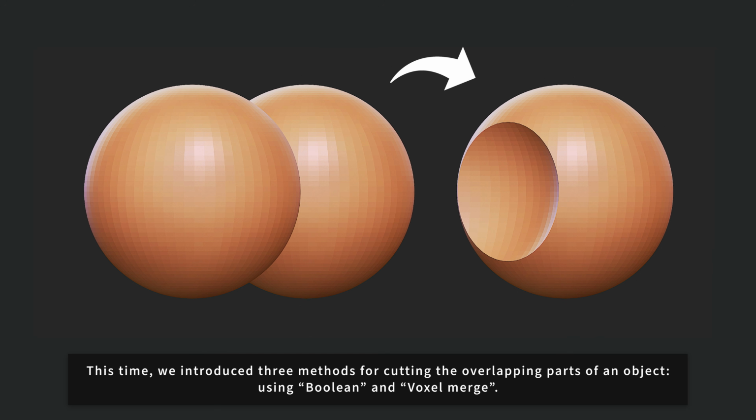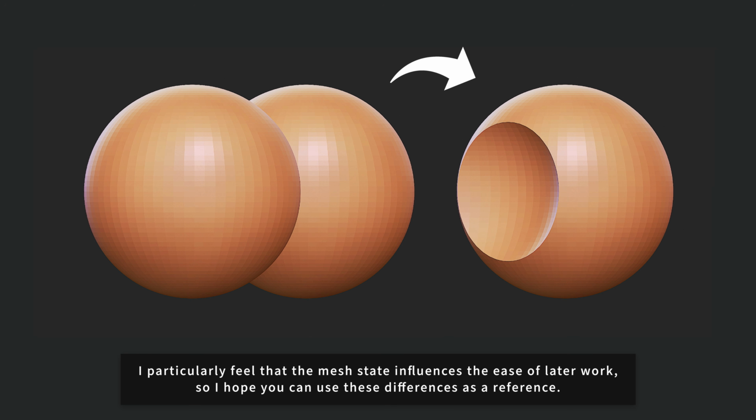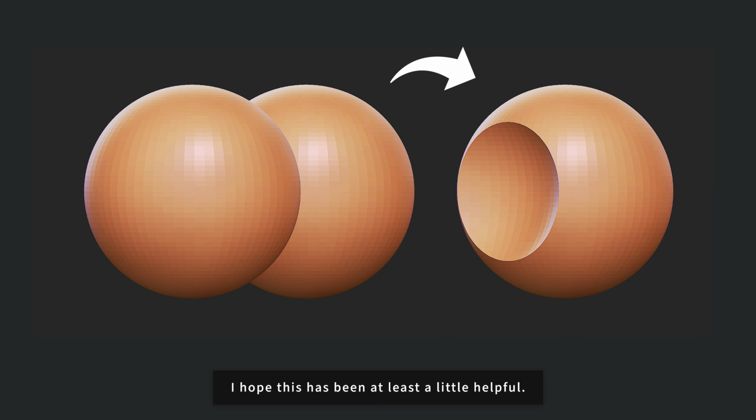This time, we introduced 3 methods for cutting the overlapping parts of an object, using Boolean and Voxel Merge. Each method results in different finishes and mesh states, so please use them according to your needs. I particularly feel that the mesh state influences the ease of later work, so I hope you can use these differences as a reference. I hope this has been at least a little helpful.